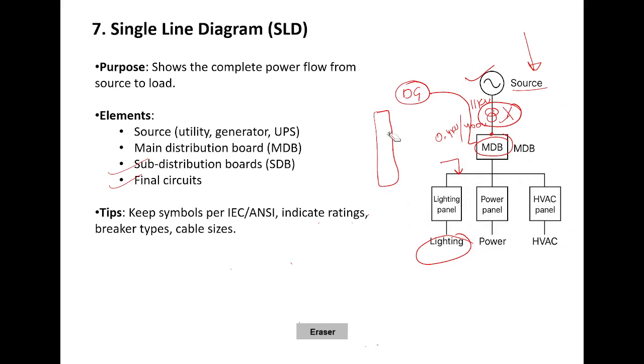But if you are working on international projects or government projects, you need to follow international symbols, or you can use your local symbols that are defined by your government. So keep symbols as per IEC, which indicate rating, breaker types, or cable sizes. So this is very simple.